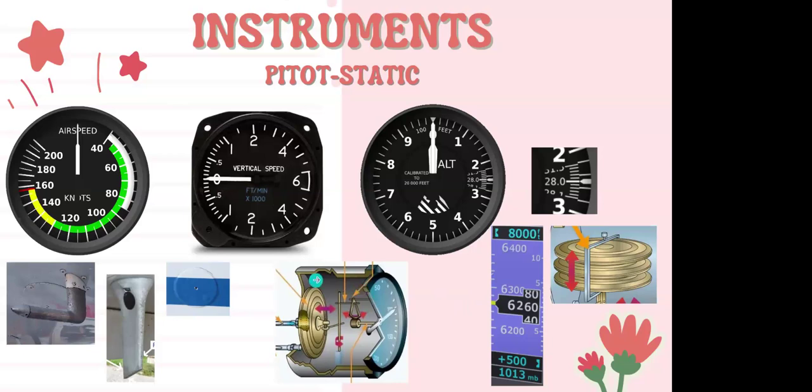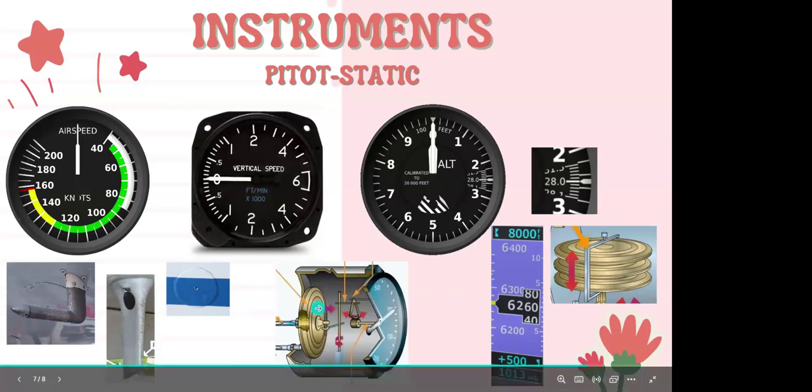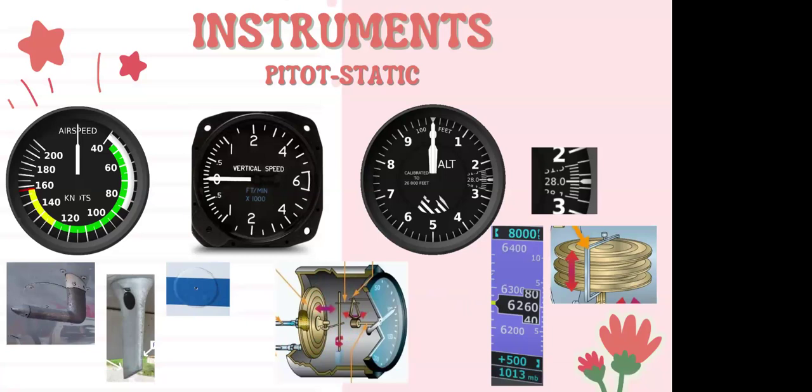Well, it's similar to how the airspeed indicator measures pitot against static. Inside, it has a diaphragm. It also has a line to the case. So in the VSI, we have two separate lines coming from the static port, one feeding into the diaphragm and one feeding into the case.